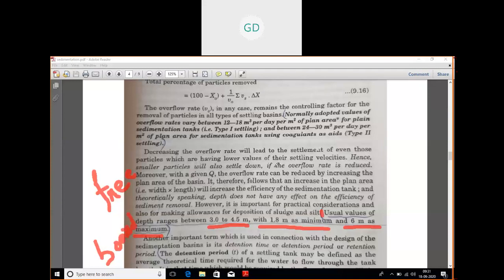That spacing is for safety purposes. Suppose people enter the tank to clean it, and some emergency or accident happens, they can put out their head and breathe. Also, it keeps the water inside the tank from touching the slab, because the slab might be dirty.